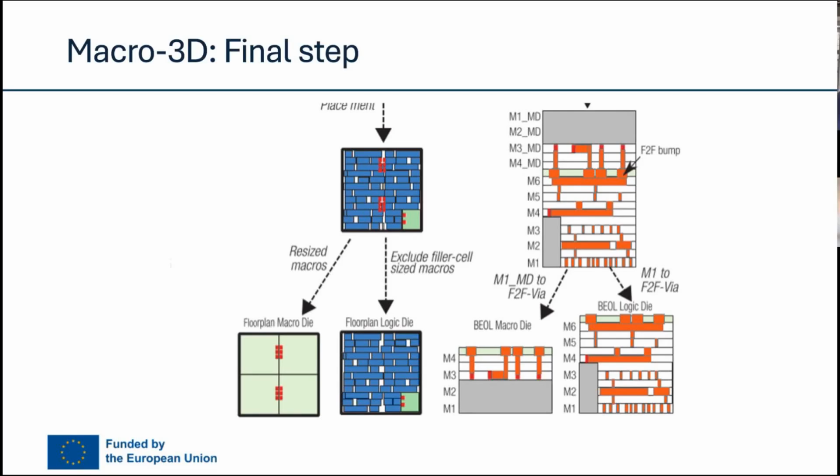The only limitation is that the location of the macros in the upper part is fixed. The two advantages that you get with that are that we have a perfect definition of the timing, and also that we can use the complete stack for the metallization even if we are using a standard 2D tool.